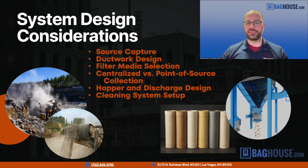Many times people think of those as different things, but a lot of the problems in cement and mining applications with dust collectors can be traced back to the discharge underneath. It goes into a screw that goes over here. That backing up or not being sufficient to remove dust quickly is a cause of a lot of the problems we see. So you have to think of all of it together: the hoods, the ductwork, dust collector, the discharge underneath where it goes, as well as the system fan, obviously, all of that together as one dust collection system. And by doing that, you can avoid some of those problems.